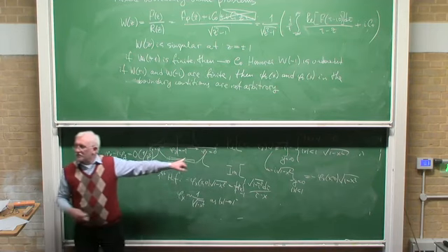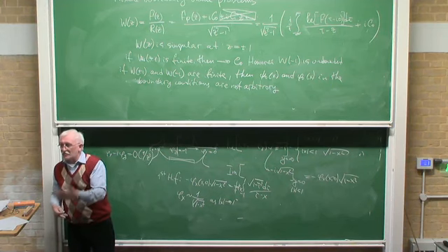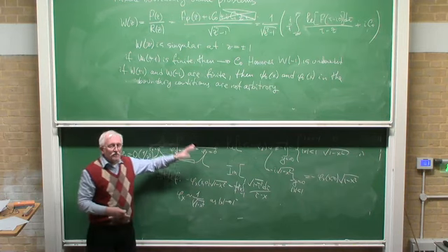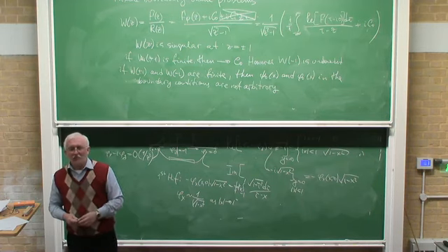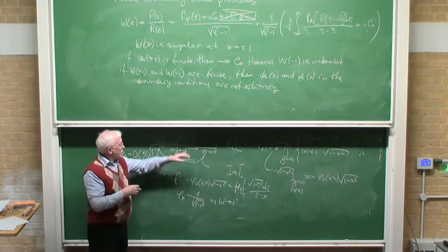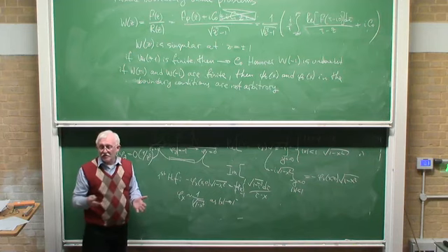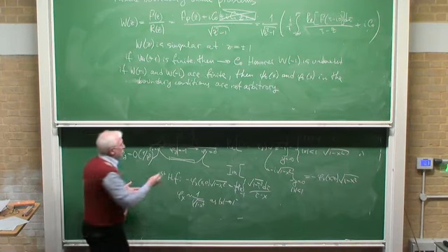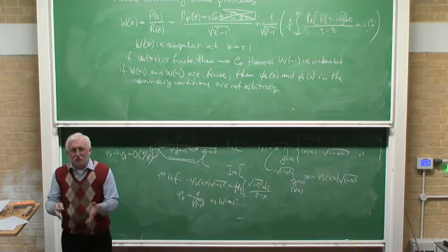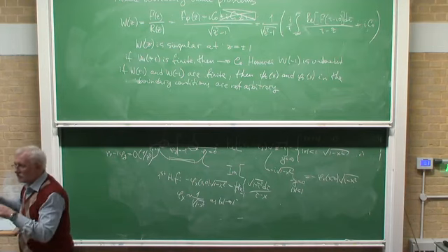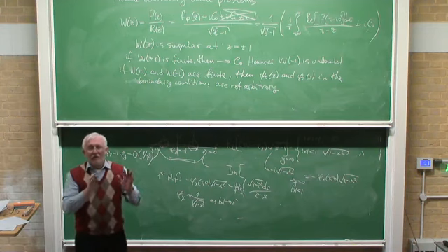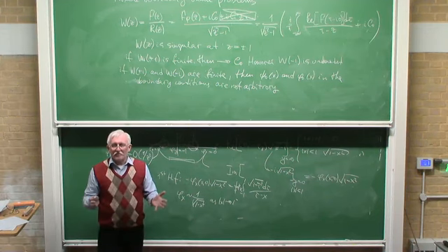Over here, once we write this condition, we do not account for nonlinear terms in the dynamic boundary condition, right? This is why it gives the problem. On the other hand, once we simplify the problem and solve it, we can find that the result is not physical only close to that point. Then we go to that point using asymptotic methods, and we formulate a local problem of the flow in the iteration and solve it.